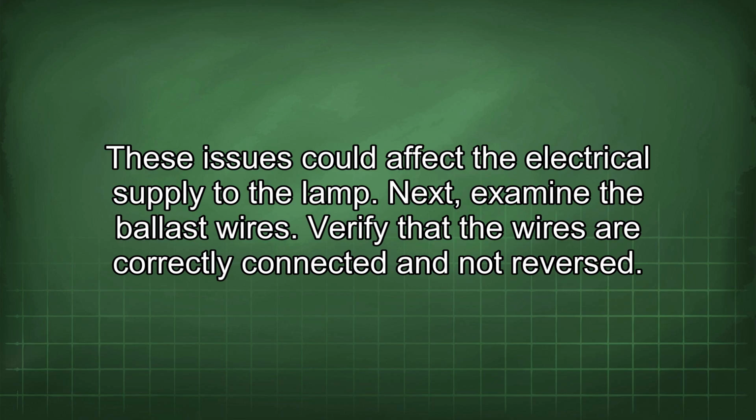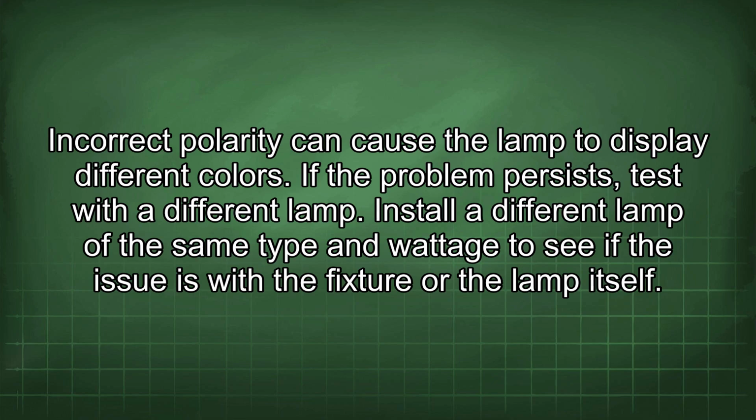Next, examine the ballast wires. Verify that the wires are correctly connected and not reversed. Incorrect polarity can cause the lamp to display different colors.